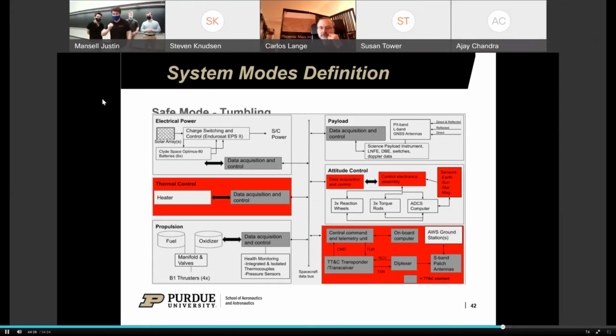We were able to get the inertia matrix from our CAD model and use that in our attitude dynamics, but it's hard to model how that changes over time. So we were just trying to make sure we accounted for a tumbling mode, and at the very least had the capability to continue communicating and debug in a tumble. I don't know if you have any recommendations for changes to our design to minimize that risk.